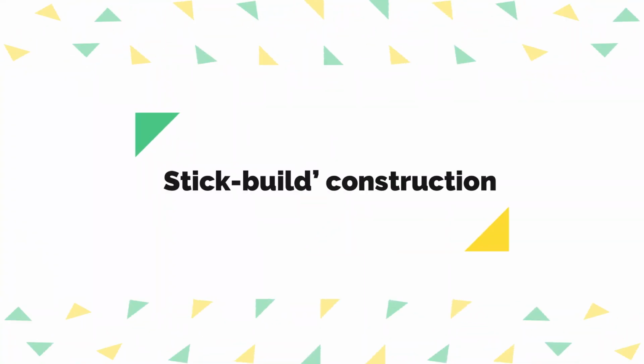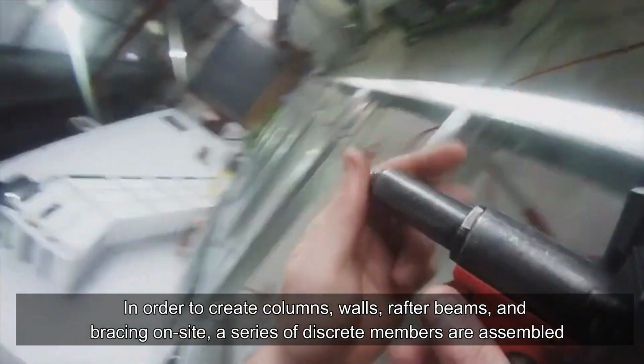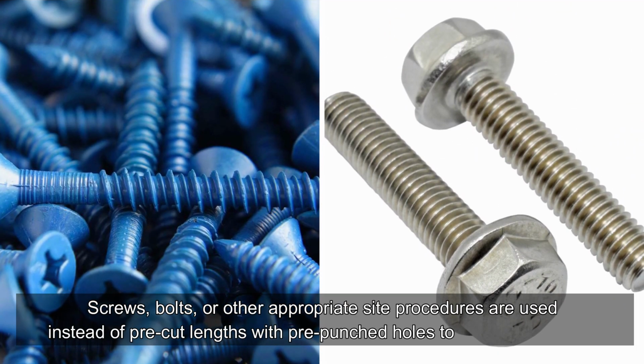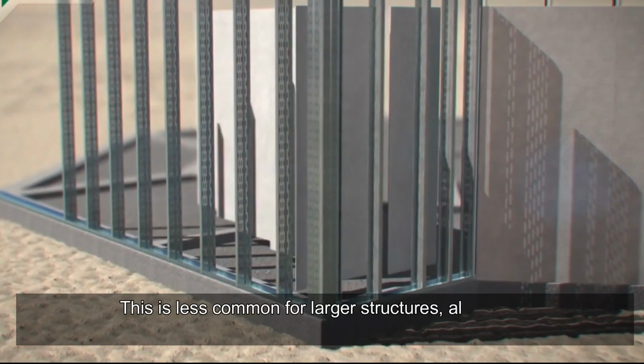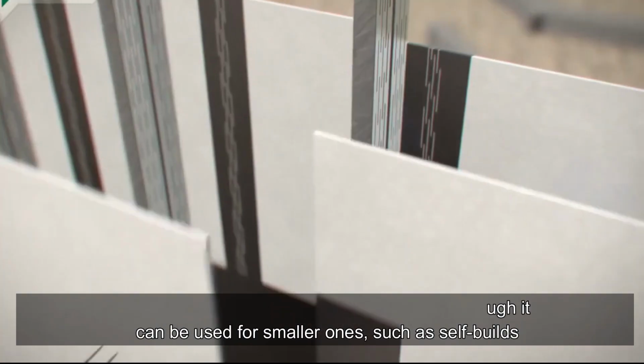Stick-built construction. In order to create columns, walls, rafter beams and bracing on site, a series of discrete members are assembled. Screws, bolts, or other appropriate site procedures are used instead of pre-cut lengths with pre-punched holes to make connections. This is less common for larger structures, although it can be used for smaller ones, such as self-builds.